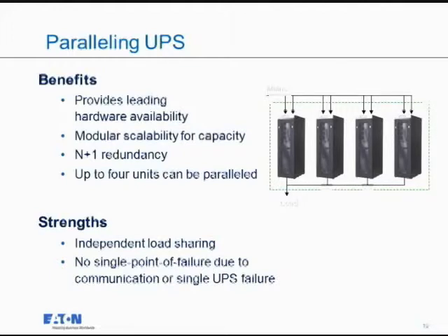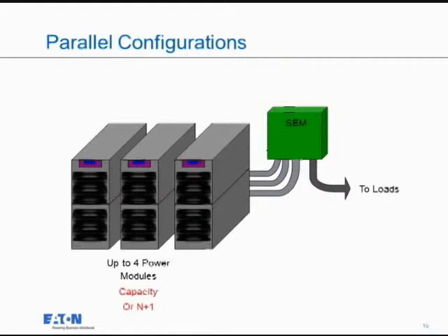When we get into smaller applications, this is a 10 kVA or a 20 kVA application, our tie point actually becomes a 12-pole distribution panel, where the UPSs feed into the panel, and the main bus of the panel is the tie point. How many people here have panels?